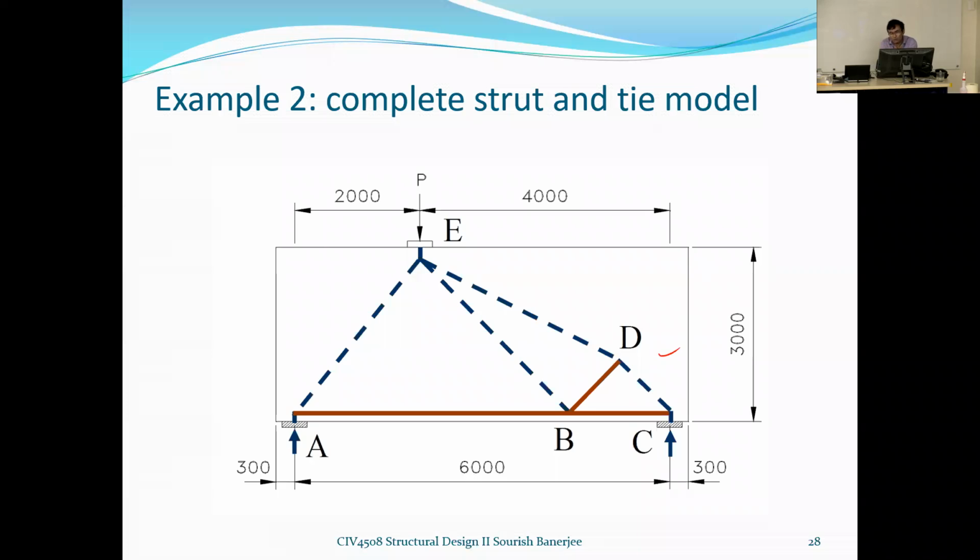You can see this one. This is very important. Follow the guidelines, because according to the guidelines, if you have two slant members, then it doesn't work. So as a result, we need to have an alternative load path. This is an alternative load path in this case.